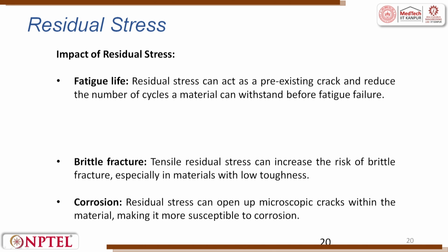So, fatigue life, the residual stress can act as a pre-existing crack and reduce the number of cycles a material can withstand before fatigue failure. So, this generally happens with gears, where two gears are mating, and where there is a chain and a sprocket. So, where there is a bearing, everywhere this fatigue life comes into existence, how many cycles it can withstand.